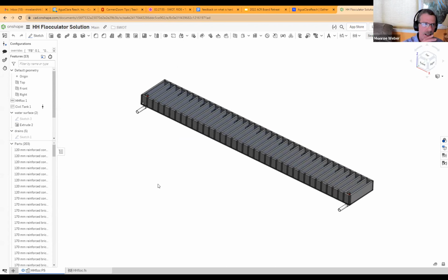In the horizontal vertical flocculator that we use most, the water goes up and down one channel, and then goes through a little port, and then goes up and down, up and down in a second channel, or maybe even a third channel. But here, there's only one channel. It's just baffle, baffle, baffle, baffle, baffle in a straight line all the way down to the end.